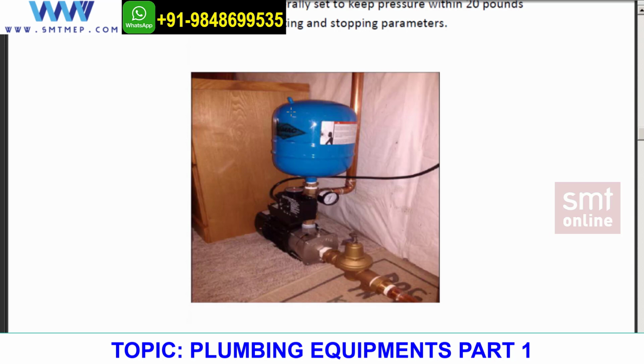This will compress the water and send it to the respective fixtures. So this will avoid the pump turning on to pump up the water. This way the pressure tank is being utilized. It saves running cost and gives more life to the pump.